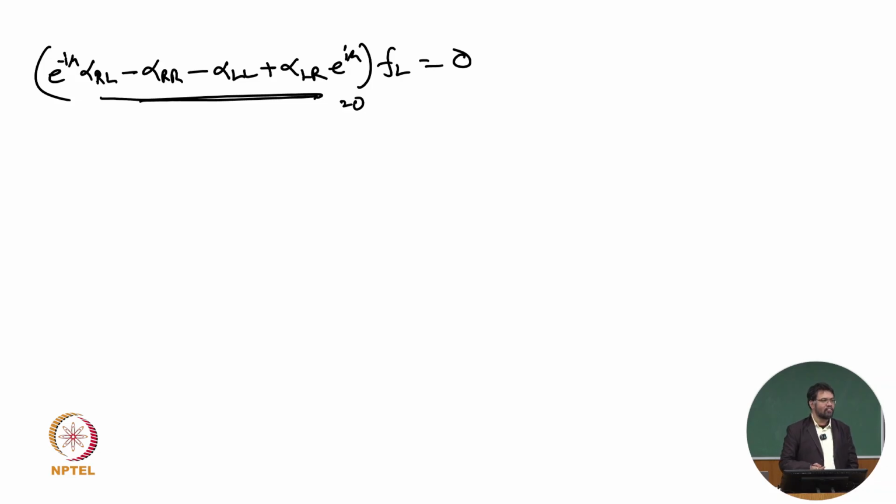Why? Because alpha is nothing but the dynamic stiffness matrix, and the dynamic stiffness matrix must contain omega. So omega means the excitation frequency, that is within the dynamic stiffness matrix, and alpha is actually the receptance, the dynamic inverse, or the receptance of the condensed dynamic stiffness matrix. So that contains omega, and e to the power of i mu we can see here, which is the wave number or the non-dimensional version of the wave number. So our target is to get mu in terms of omega.